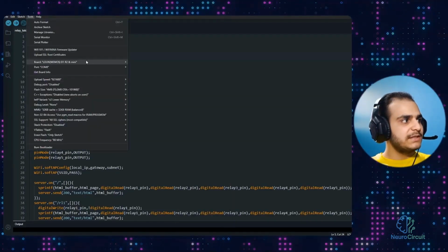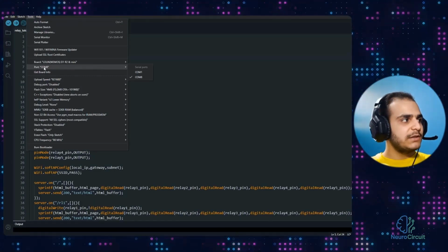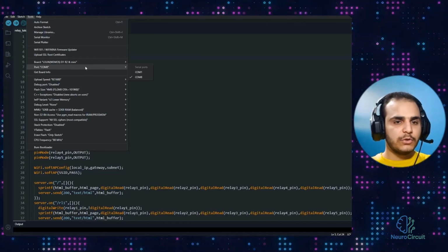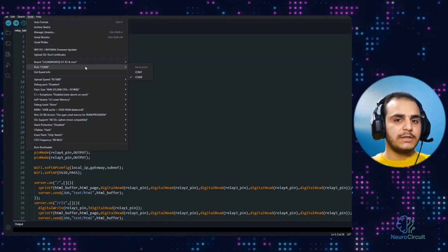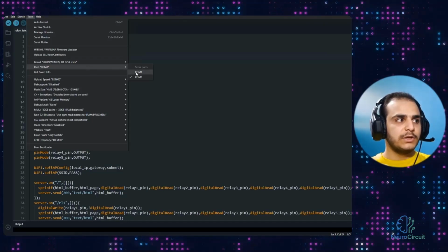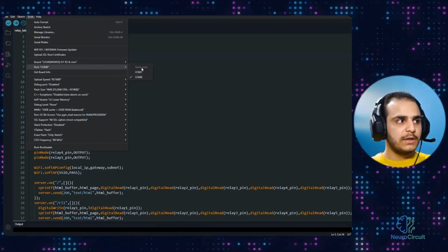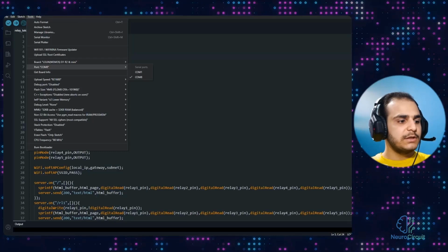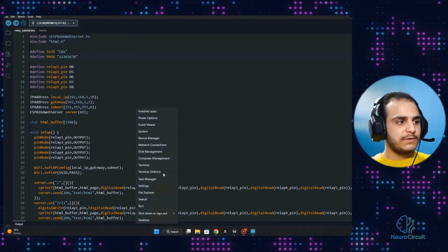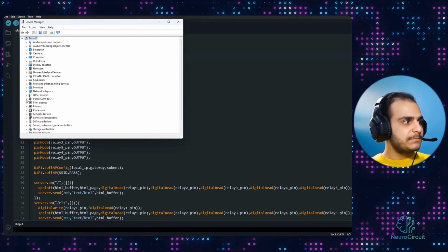So, what settings does it have? Preferably, you don't need to change any of its settings at all, and you just need to come here and select your serial port, which you'll do after you've connected the module to your system, and if it needed a driver, it gets installed and the serial port is recognized. Here, a COM port will be added for you. If you have several of these COM ports, the best way is to right-click on your start icon, go to Device Manager, and in this section, go to the Ports section.